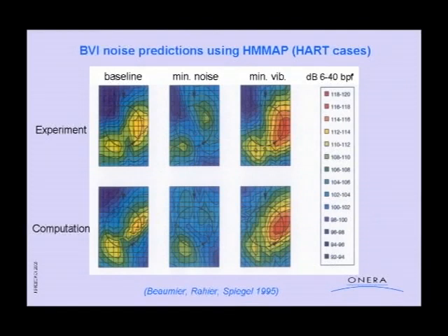And by adjusting the phase of this higher harmonic control, we were able either to decrease the noise by 4 to 5 dB, or to completely decrease the vibrations, but unfortunately this corresponded to the maximum noise with this 4 per rev, but with other frequencies it could be different.